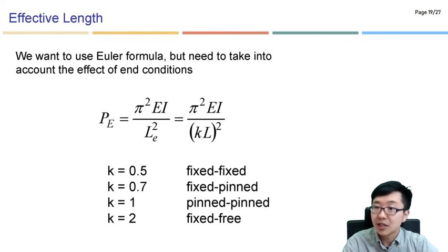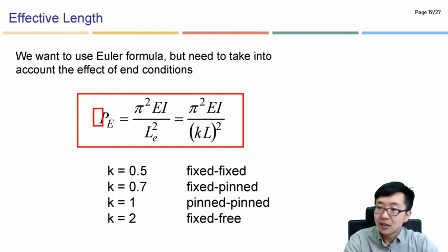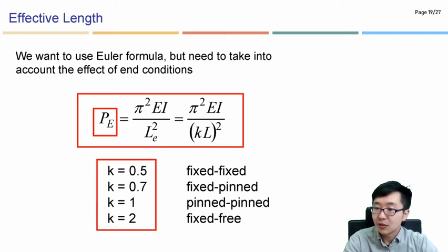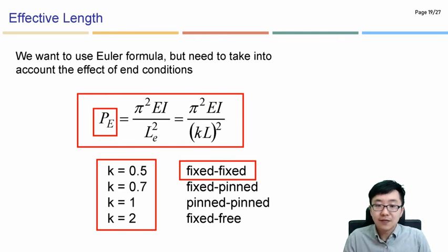So this is the exactly same information again. Once we have this equation, frankly speaking, we can do everything. Based on the boundary condition, we can calculate this elastic buckling force, and this shows the coefficient representing the effective length. Based on this, we can see that the K value will be varying. So for the fixed condition, you should understand the physical meaning now about the coefficient.